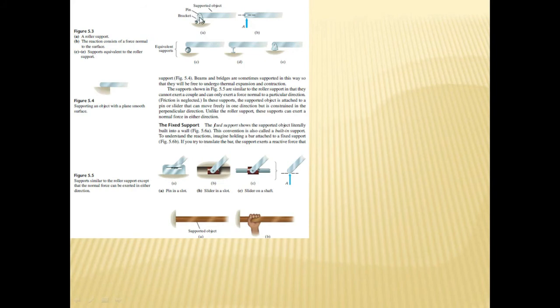But if you look at this roller over here, this roller cannot move in the vertical y-axis direction. Even if you want to move it with your hand, because it will be fixed in the ground, this roller will be fixed with the capability to move along the x-axis. So this roller will give you a reaction A. It cannot be moved along the y-axis. Even if you try, the reaction A will be generated. This is the roller support A.